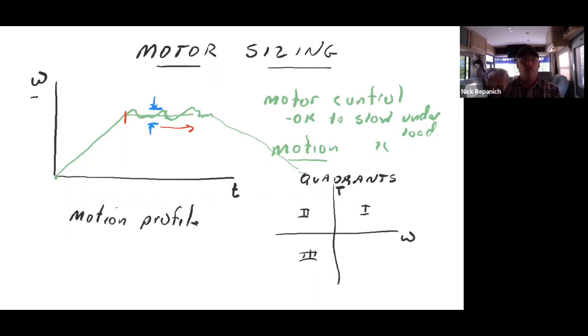It may decelerate faster at the end or faster at the beginning, depending on what load is against it. If it's a pure frictional load and it's an even load, it's probably going to be pretty linear. If it's an aerodynamic load, aerodynamic has more force at higher velocity. So an aerodynamic load might cause this to slow quicker as you decelerate.